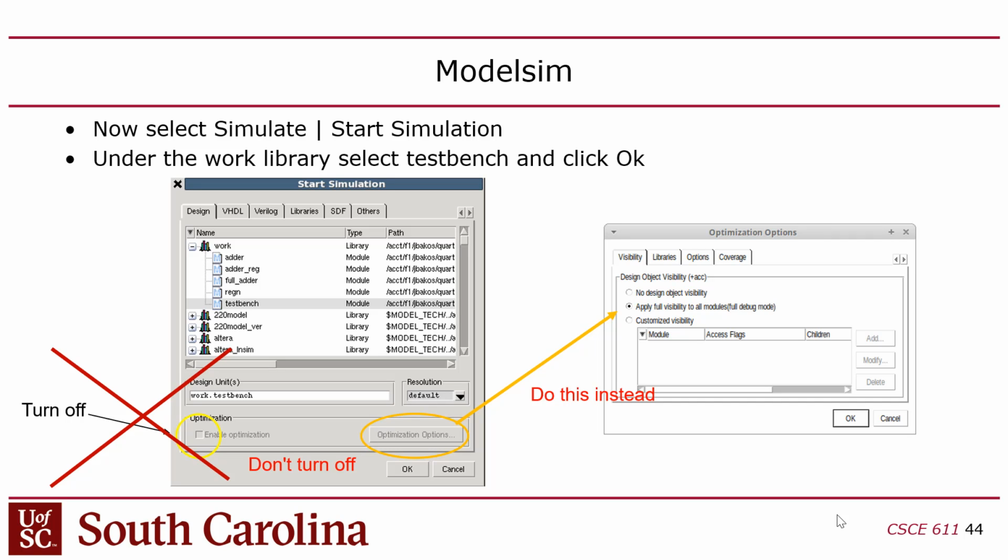When you want to simulate, you have to tell it you want to simulate, and you have to give it the top level module you want to simulate, right? And so now you might say, what about the other modules? Don't worry, they'll get included, but that's done automatically. You just say simulate, like for example, in this case, the test bench, and all the things that are part of that test bench design will magically be sucked in through their module name, right? So you only have to tell it to simulate one file, even though you're really simulating multiple files.